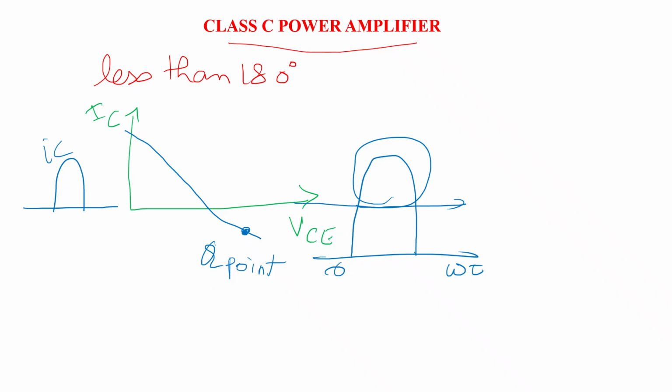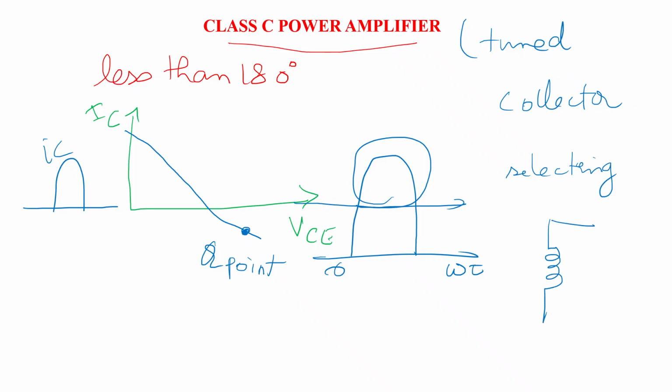Tuned amplifiers, yes, these Class C power amplifiers are also called tuned amplifiers, in which the tuning circuit is connected to the collector terminal of the amplifier. These amplifiers are employed for the purpose of tuning. Yes, tuning means generally selecting the variable frequencies. Yes, that is, the tank circuit will have an inductor and a capacitor circuit like this with L and C components.